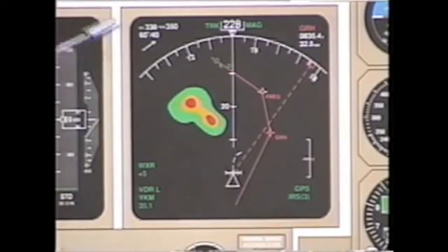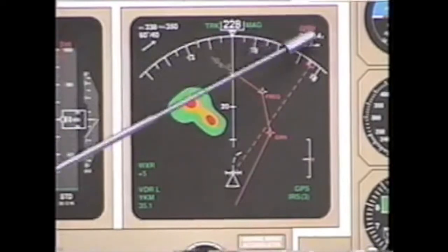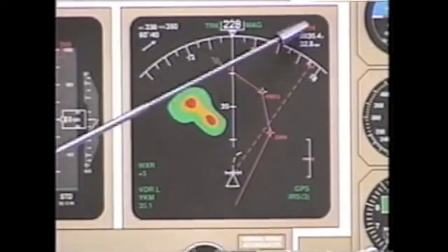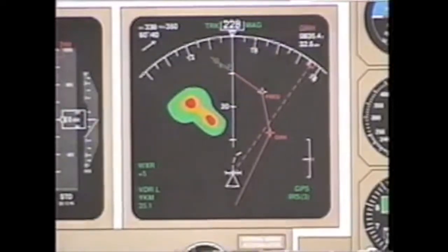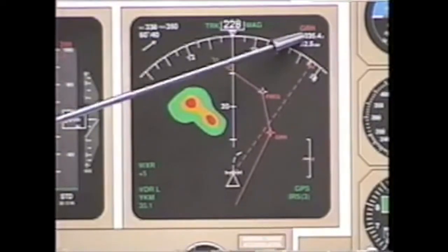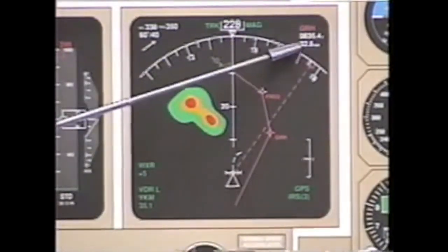In excess of 100 knots, we pick up true airspeed and wind information, direction and velocity with the direction arrow. Upper right-hand corner, regardless of the range you have displayed on the nav display, the active waypoint will always appear in the upper right-hand corner. The time at which the FMC computes you get into that active waypoint and how far away that point is.